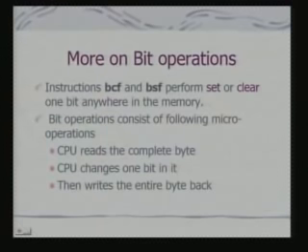So, the instructions we have seen, BCF and BSF, perform set or clear of one bit anywhere in memory, and bit operations consist of the following micro operations. The CPU reads the complete byte, the CPU changes one bit in it, and then writes the entire byte back.